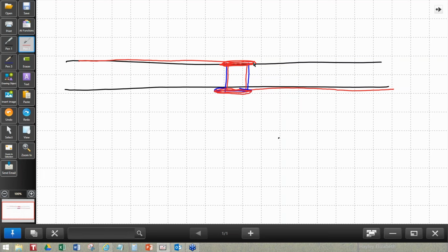We probably could come along and say, let's pass a current through this, and that current will flow down through the barrel, and it will come out the other side. So we know what the current is, but what is the drop across this? We pretty well know how to calculate the resistance of a trace, because we can take its width and its thickness and calculate its cross-sectional area and then multiply by the length and the resistivity of copper. But what about vias? Well, for DC currents, it turns out to be very, very similar.